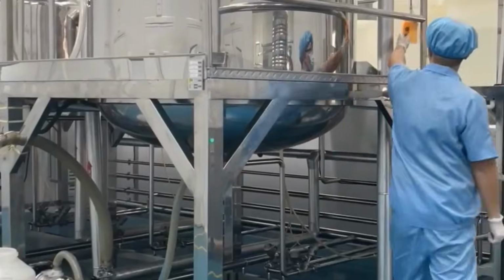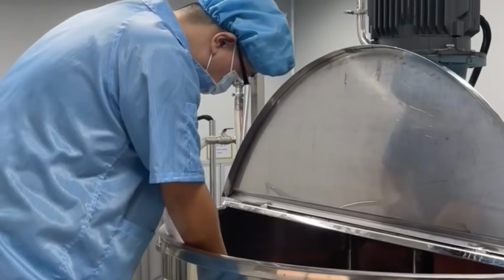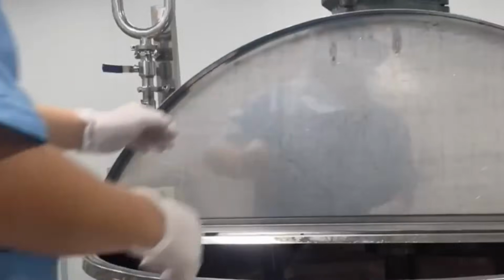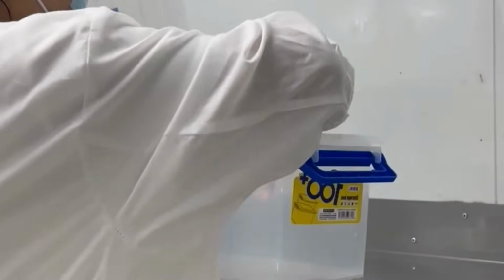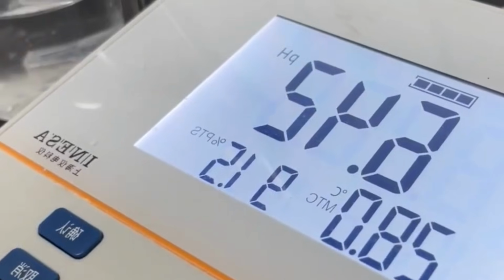Throughout the entire production process, data is logged by a centralized manufacturing execution system. Ingredient usage, batch ID, tank temperatures, pH levels, fill weights, and cap torques are recorded in real time. Deviations outside of tolerance trigger automatic alarms and halt affected processes.